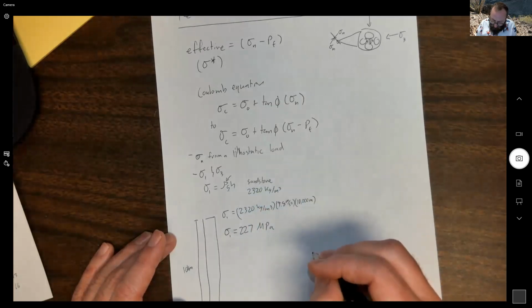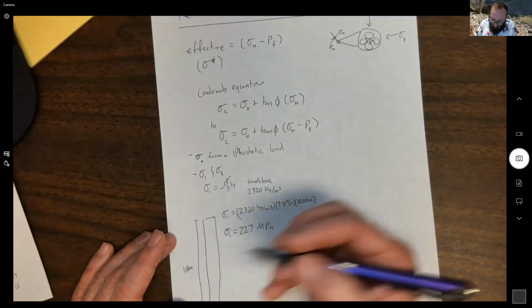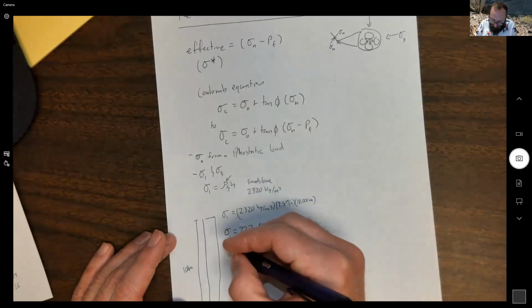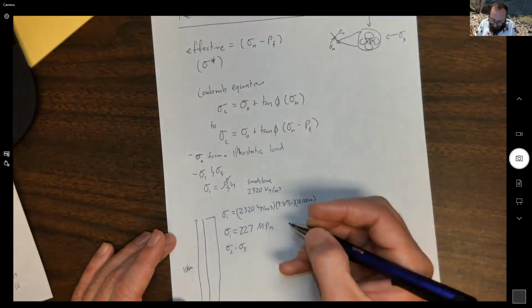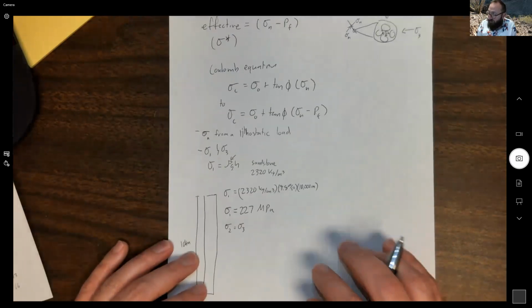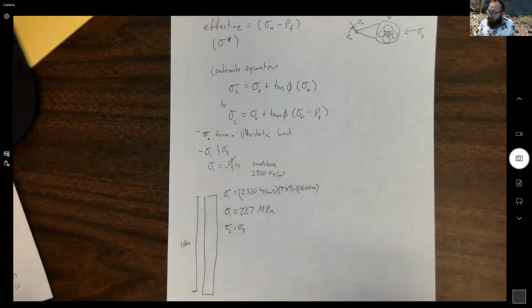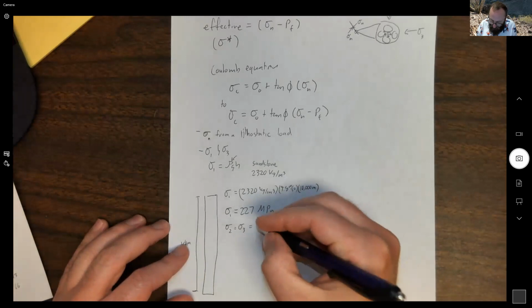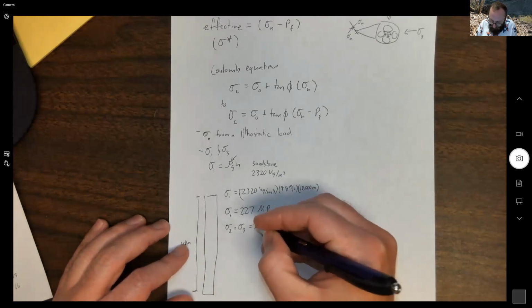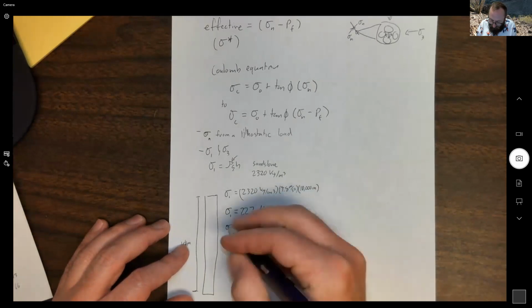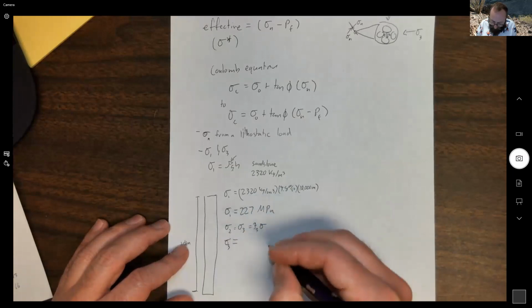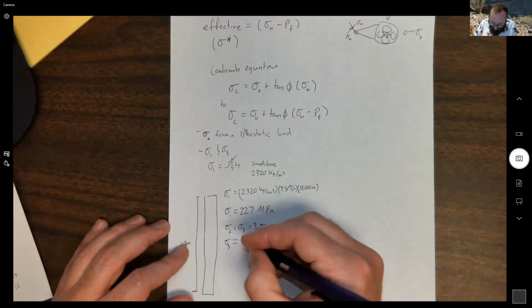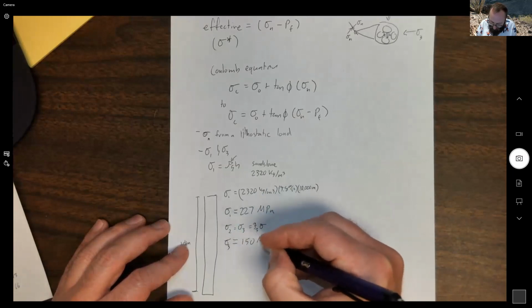megapascals. And so let's just operate on the assumption that we don't have any additional horizontal stresses, in which case sigma 2 and sigma 3 are equal. Okay, and we're just operating off the assumption from our earlier discussion of Young's modulus. When we compress our rock, it's going to get pushed back against. And usually that means this is about 1/3 to 2/3 of sigma 1. So we're just going to operate off of that assumption, which tells us sigma 3 is going to be 150 MPa. Okay, our confining stresses.